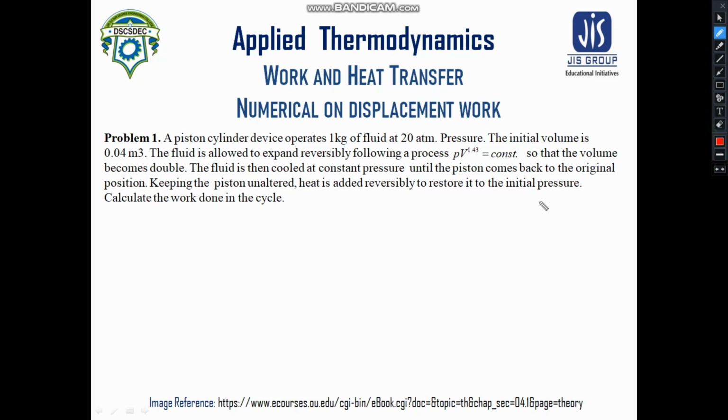This is a non-dissipative kind of work, and you have to remember, every time this work is done, the quasi-static equilibrium is always maintained here. So this is a non-dissipative kind of work, and for each process, for each state, the quasi-static equilibrium is maintained. All of this is hypothetical, but we have already told you that this thermodynamic equilibrium concept and the quasi-static process, these two are the primitive assumptions, and they are very important.